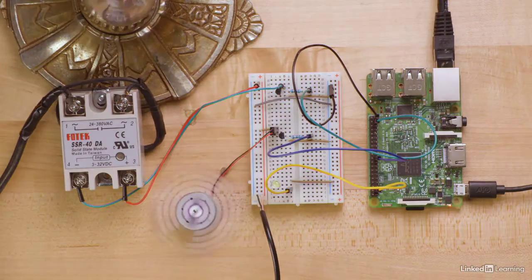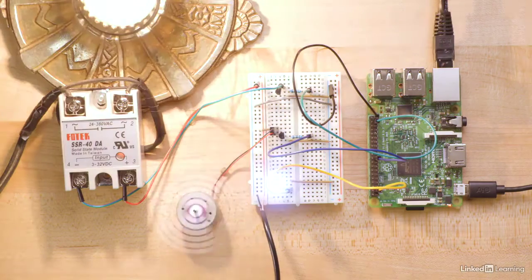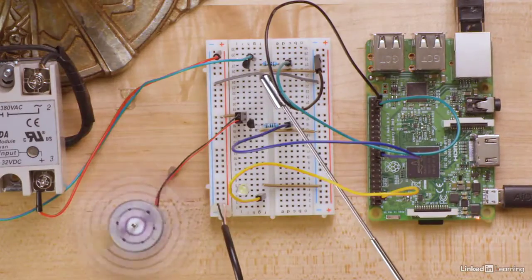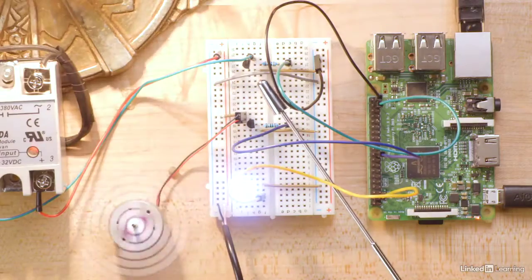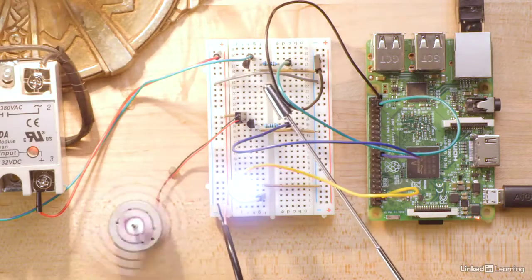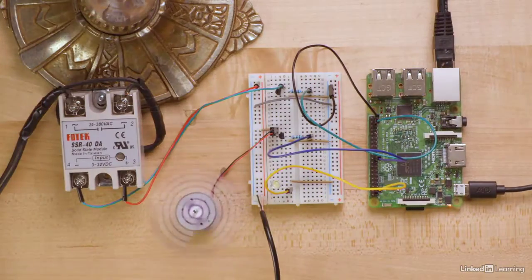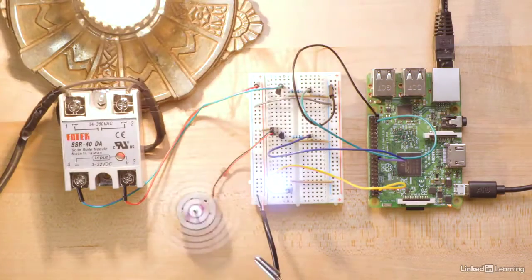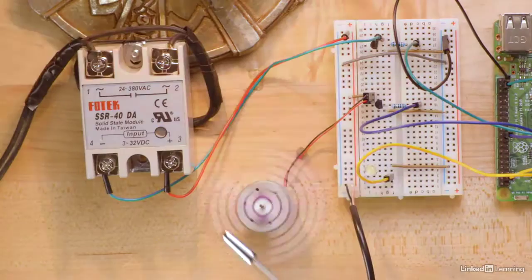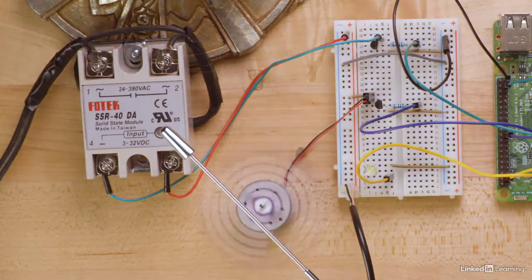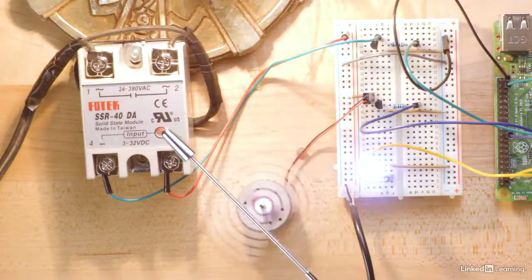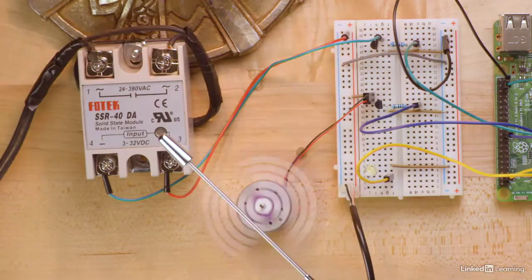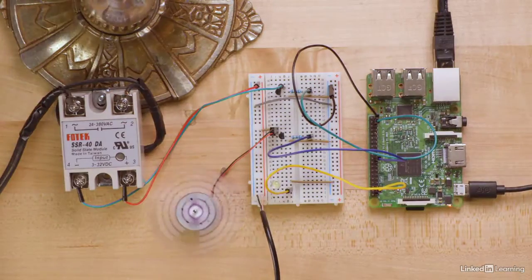Now, what about controlling a larger voltage, say house current? The 2N3904 transistor in this circuit is only able to handle about 40 volts. After that, it explodes or melts. We could use a larger transistor, but that would require more current. Instead, we can take the same circuit we used for the motor and control something called a solid-state relay. A solid-state relay can handle 380 volts and 10 amps, possibly more depending on the device.